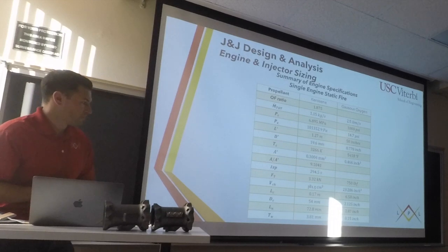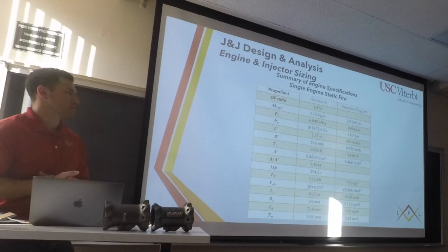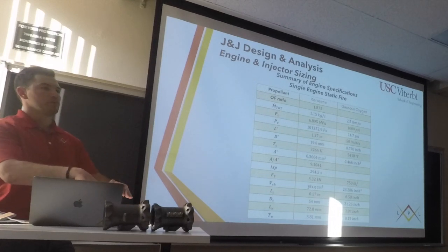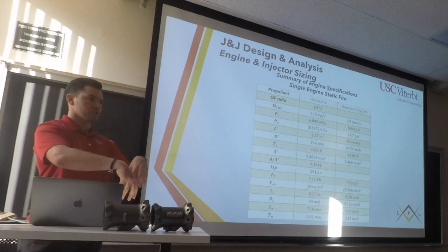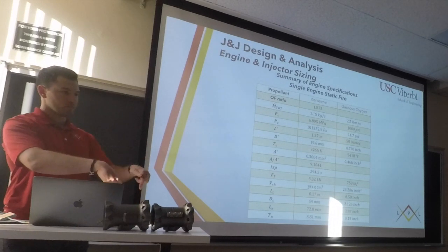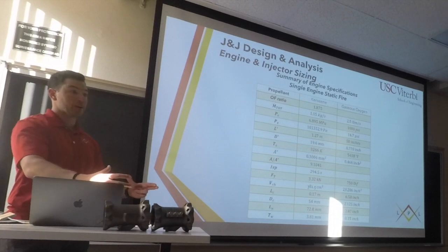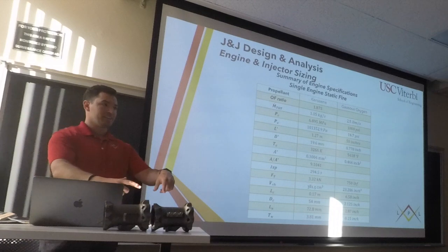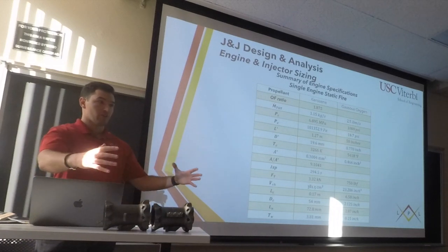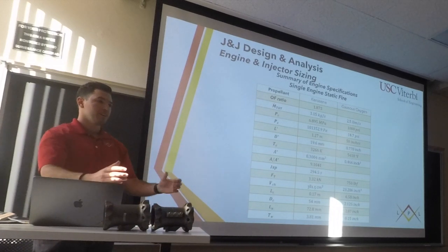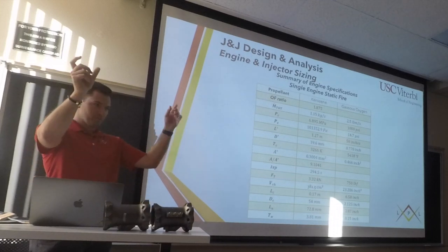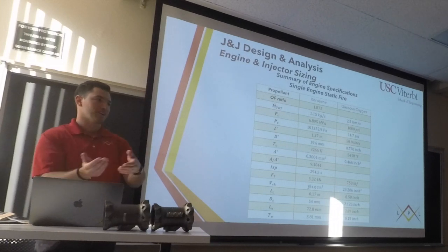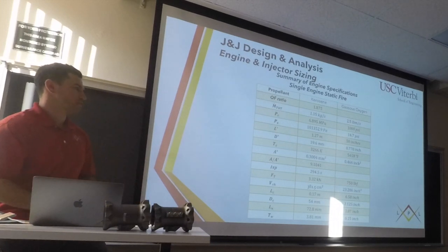But there's a lot of things. In terms of figuring out the optimum exit area, right? You want P equal PA, but if you think about it, like the Falcon 9, for instance, there's 9 engines. But if you wanted the most optimum exit area, it would be bigger actually. So you would have a larger area. And so if you have 9, now the whole vehicle needs to be larger to compensate for those 9 little areas. And then now when that's bigger, the walls need to be bigger. And now all of a sudden it's more mass, and it's like, oh crap, thrust to mass is not worth it. And then it's just all iterations.